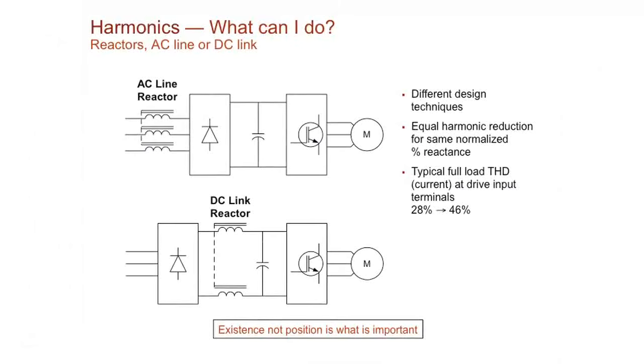The one thing that we do have is our swinging choke, and we'll talk about him. The benefit to him is when he's lightly loaded, you still get a higher harmonic mitigation than you would from a standard DC choke.